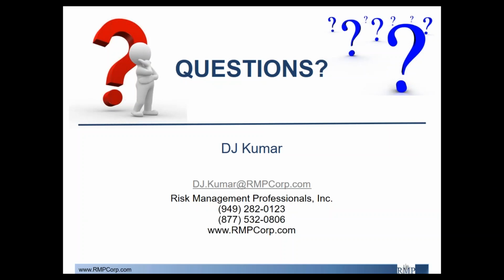All right, we do have a couple questions. The first is, what is the difference between P&IDs and PFDs? Okay, it's a good question. P&IDs and PFDs are often confused. I know when I was in school, I would confuse them early on in my engineering career. One way to think about the difference is that a P&ID is just a more complex version of a PFD. A PFD doesn't always show what's available on the P&ID, and it will often just show the flow direction, the basic chemicals being used, and maybe the properties of the chemicals being fed into a system, along with the equipment. It's just a generic overview of the entire process, whereas a P&ID is more intricate and shows major equipment and some major loops and minor loops in the system.